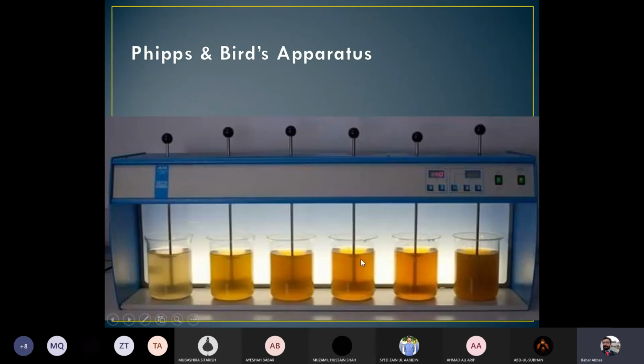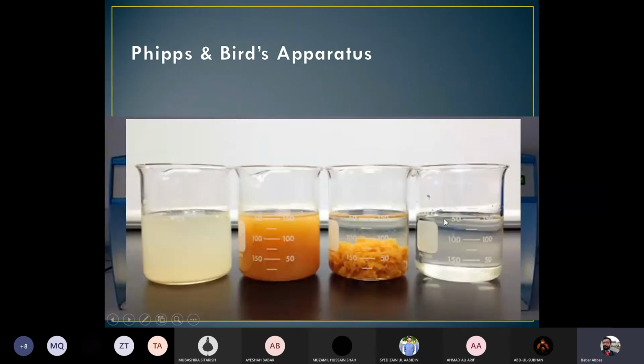From all these beakers you have to study all parameters in terms of this array. This was the basic of beaker one. After the basic, you added coagulant, so that is step 2 of beaker one, step 3 after coagulation, and step 4 of beaker one after sedimentation or removal of the suspended particles from the system.